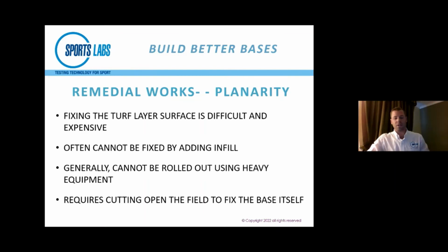We've seen people try to roll it out with heavy rollers. That almost never works. We've seen them try adding infill to bring up the level. All that leaves is a dark spot there. That doesn't help at all. And honestly, that goes back to the aesthetics. It just doesn't look good at the end either. So it's very hard to fix planarity issues after the fact.